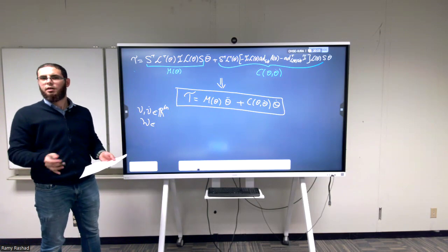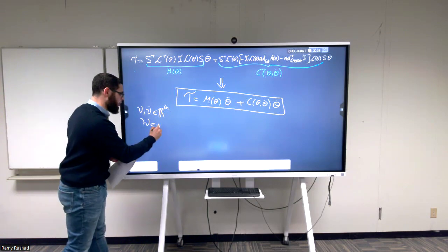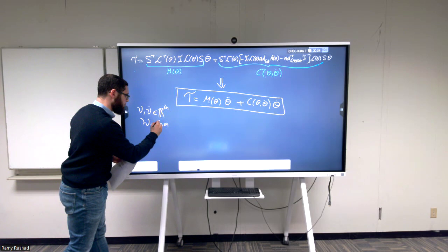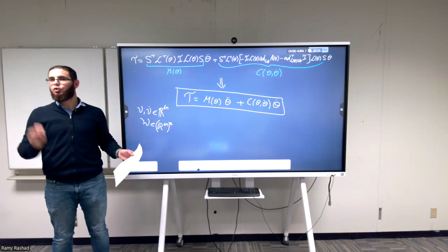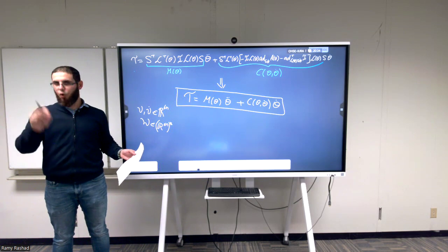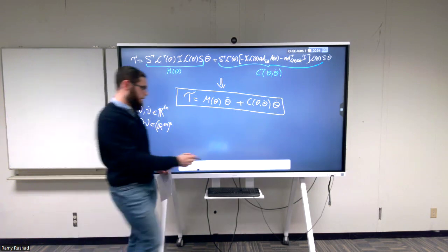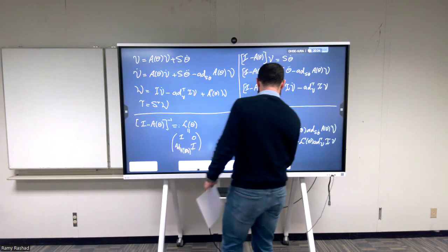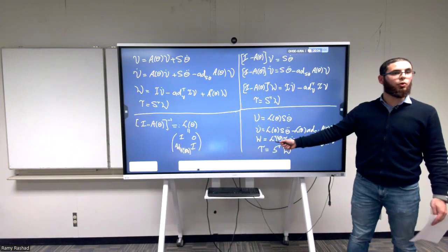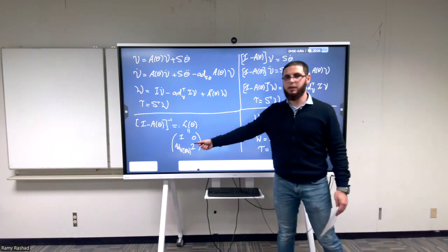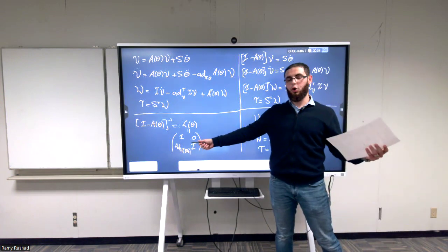What about the range? Of course, it's the same. It's just for notational purposes. Remember what we called it? We just called it a dual. Why did we do that? To emphasize it is a covector, not a vector. You see it clearly here in the wrench equation, which gets L transpose. And the L here is definitely not an orthogonal matrix.